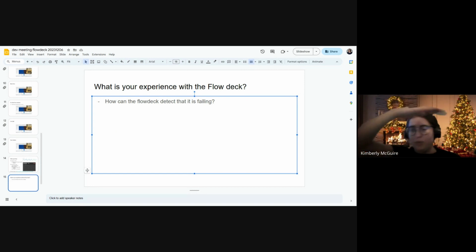If you were flying at 2 meters, for instance, then the floor is going a little bit slower, and then suddenly you have a table that moves a little bit faster because it's closer to the Crazyflie, and suddenly you would detect more flow, even though the range sensor may still be detecting the floor or something like that. So that's an interesting thing to actually try out. Because usually if you fly over a table, it would just go floop.